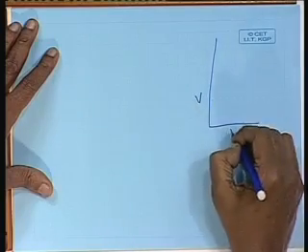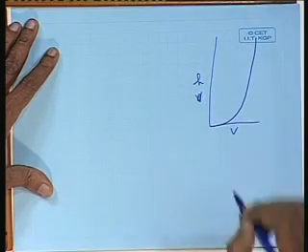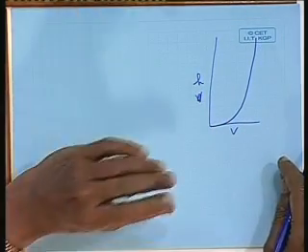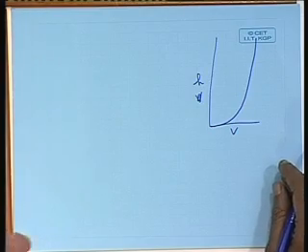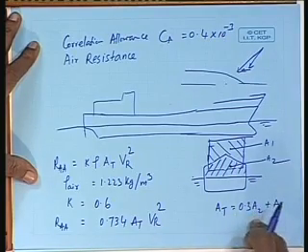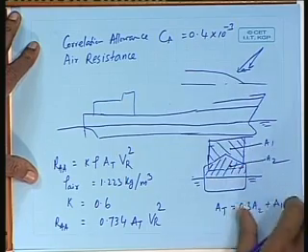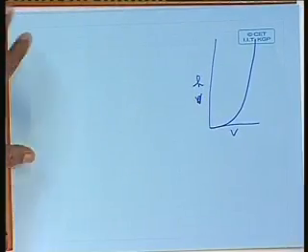So, if I draw height and wind velocity in this way, then wind velocity will go like this. Okay. So, therefore, the area near the water surface will have less effect than air far away. That is why in this A_T formulation this is taken into account by reducing the lower end of the area. Okay. If there is a tall ship, then you must calculate the height based on this formulation.